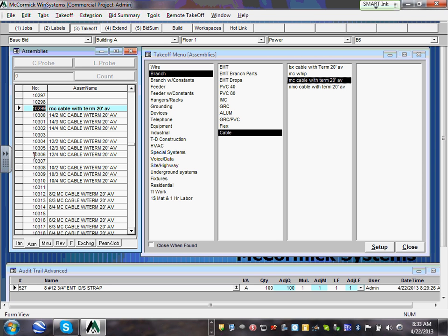If you did not circuit them right in your project, guys, take them as if they were circuited right, because you're the electrician, you're going to wire them. If the engineer did not put the circuits like 1, 3, 5, okay, that's a multi-wire branch circuit. If they're not 1, 3, 5 in one area, make them 1, 3, 5 when you take them off, because that's how we're going to do it. A good electrician saves you money. So you're going to be taking them, guys, as 4, 12.4.